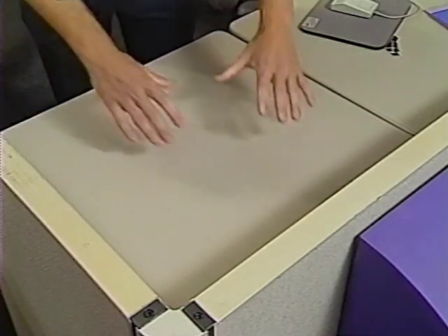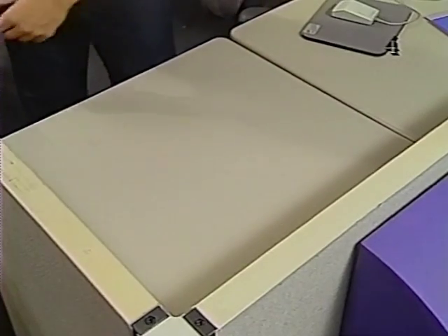Begin setting up the Personal LaserWriter by choosing a good location. Choose an efficient work area that also meets the physical requirements of the printer. The Personal LaserWriter should be placed in a well-ventilated area away from direct sunlight. Ordinary household current is all that's needed to power the printer. Temperature should be kept from 64 to 77 degrees Fahrenheit and humidity between 30 and 70%. Choose a flat, stable surface area for the printer.